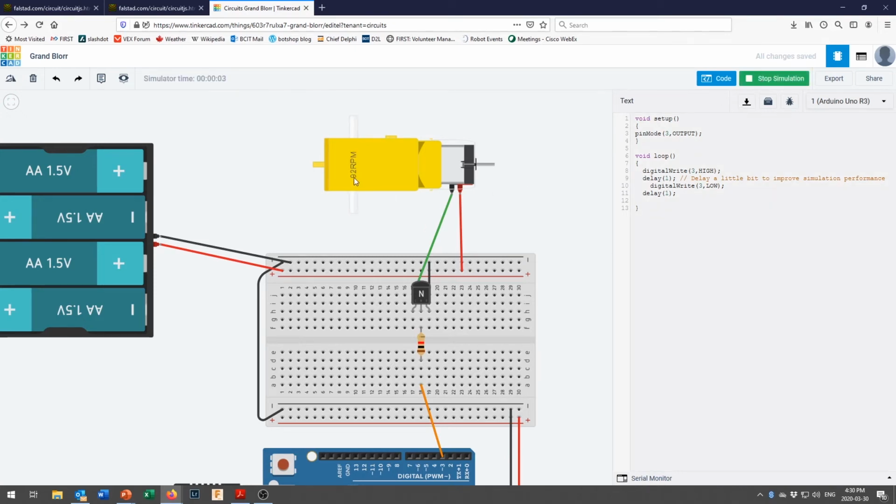And you can see that instead of having the RPM flash back and forth, it's settled in at a fairly steady 90 RPM, which is about half of the 187 that we were getting when the motor was on full time. So that's because right now the motor is on only half the time, but it's turning on and off in such tiny little bursts that we don't even notice it.